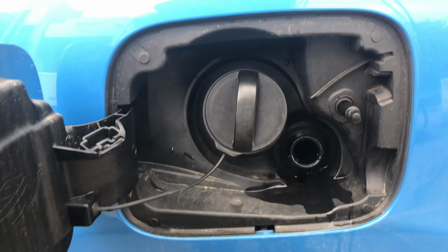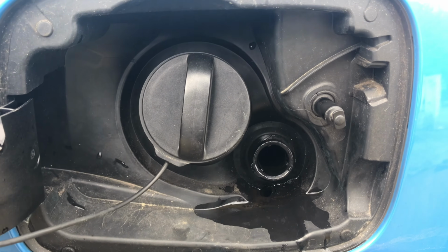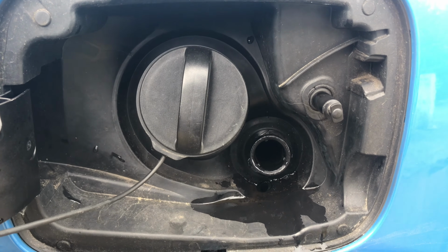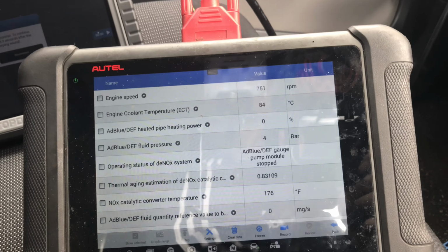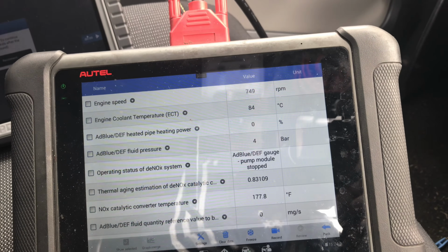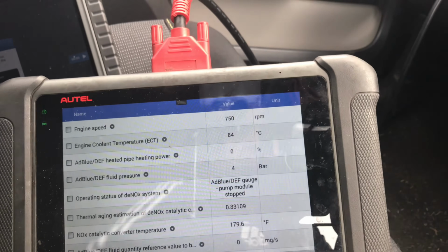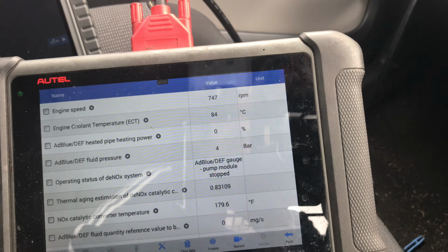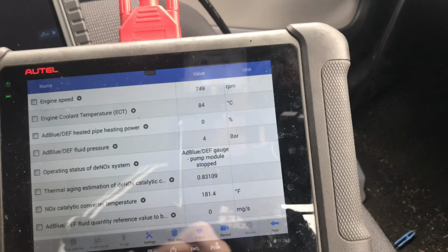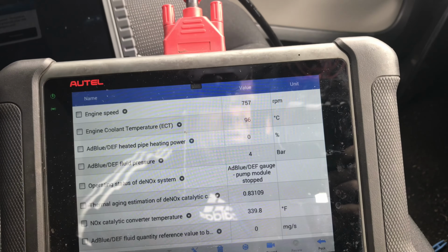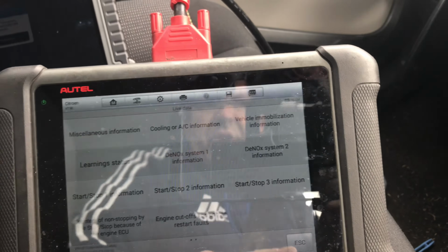Dude, this tank will not even take any. It is absolutely full. So I wonder if there's something up with the level sensor in the tank as well. Next stage. New injector back in again. So I've installed it, told the car we've got a new injector and reinitialised it. So we're sitting at 4 bar this time. Let's drive it till we get up to 80 and see what happens now. I've not got the pressure to build yet, so it's still at 4 bar. But let's try these tests again with this new injector installed.